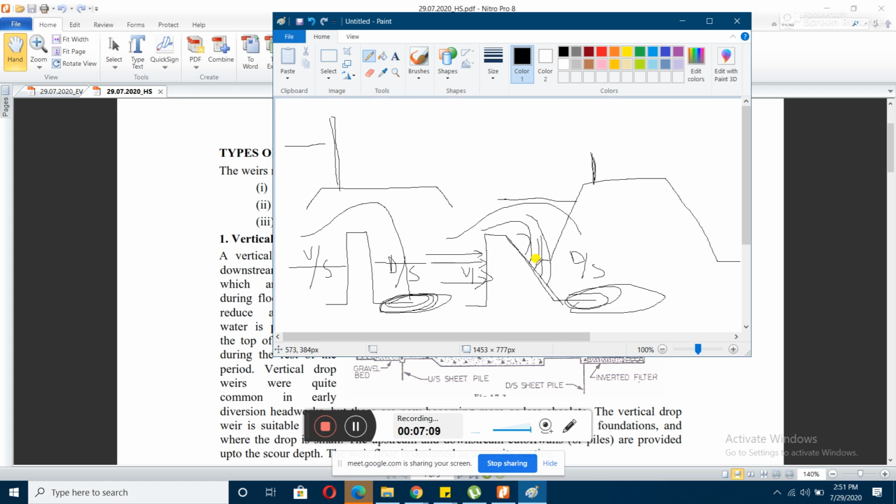So with this wall, you can see that there is not much of a hydraulic jump. The water coming from this will just get onto this face, and there is not much of a jump. So this was adopted, and the floor here does not get affected. After that it was further observed that the river is coming in this direction and hitting this wall perpendicularly, and you know that perpendicular impact is the highest impact.